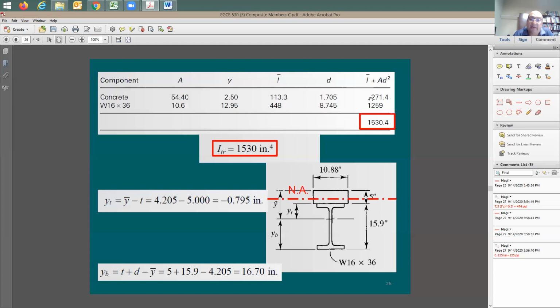If you are doing a design case, you ignore it. You ignore any concrete in tension. If you are doing detailed analysis and research, you should not ignore it. You would consider it. So it depends on the case, right? What is the purpose of doing this analysis? Now you're going to tell me, I don't know. So I'm going to tell you simply, in each problem, I'm going to be very careful to tell you exactly what the purpose of doing this is.